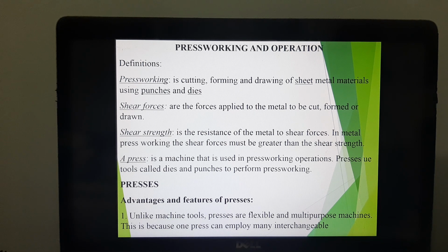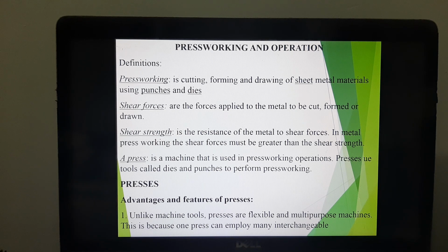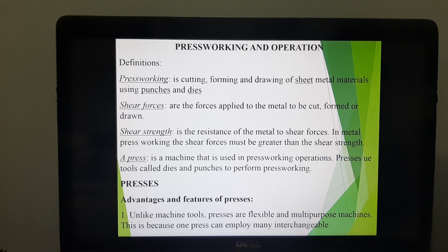Before I move on, my first question: please think about the stress strain curve and how you would fit the hot working and cold working process into it. If you remember when we spoke about the stress strain curve, the curve started off with an elastic limit, where I told you that no manufacturing processes can take place because it's just like a rubber band. When you stretch it and let it go, the material comes back to its original position. So all shaping processes take place after the yield point, which is the plastic region.